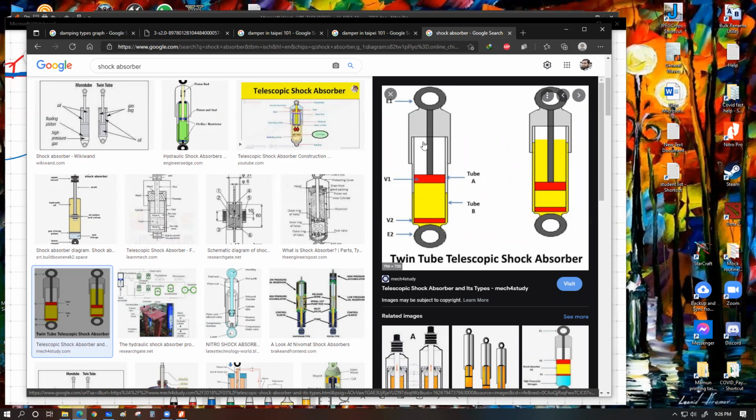So currently, suppose this shock absorber is in this condition. Now suppose from the top we suddenly apply a force. Whenever we give this force, a certain spring over here is going to become compressed, and this piston is going to go down immediately, and some oil from this tube B will flow through this red piston into the upper chamber, and this motion would be allowed with almost zero obstruction, which means there is a valve. This valve will allow the flow of this fluid really fast.